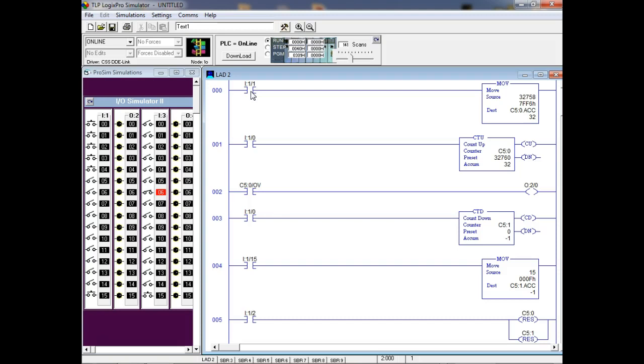Now, what I've done here is... So that -1 is an underflow at this time? Is that what you're saying? No, you have to go less than that. Our positive counters, we get an overflow if we try to go above a plus 32,767. It has nothing to do with the preset. Understand, this is the accumulator. On the down counter, my underflow, overflow.